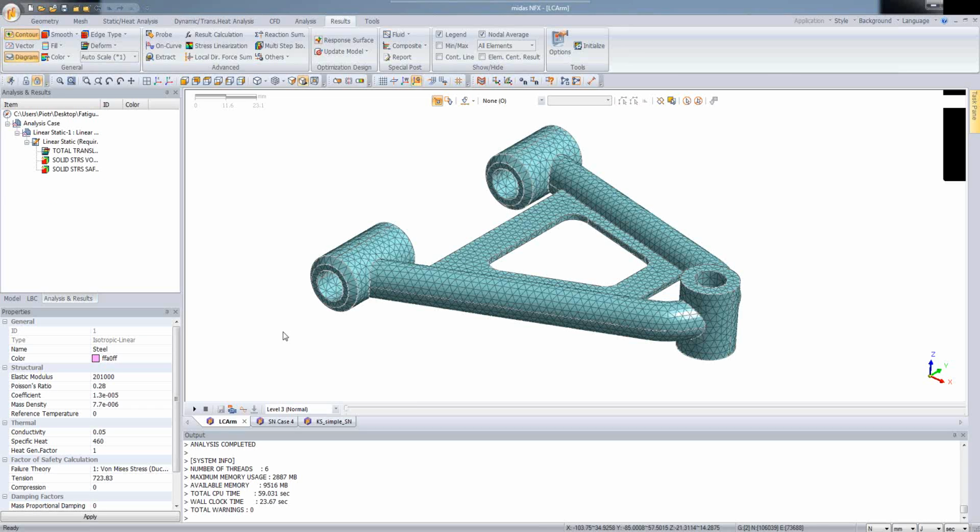The other name of this method is the crack initiation method. So this defines that the failure criterion right now is the life to initiate a crack. So we can say that once an engineering crack appears, the failure is said to have occurred.